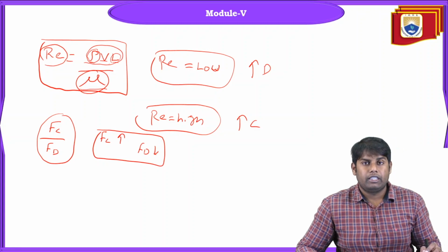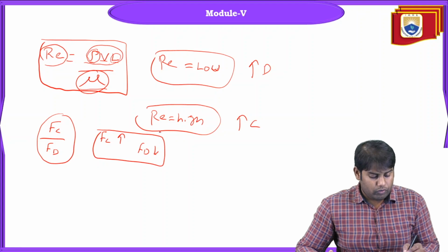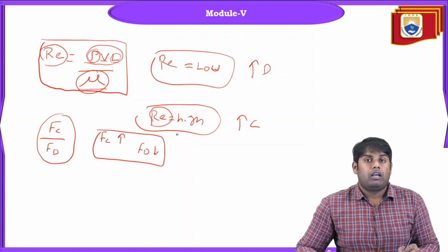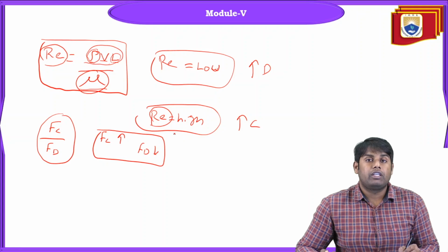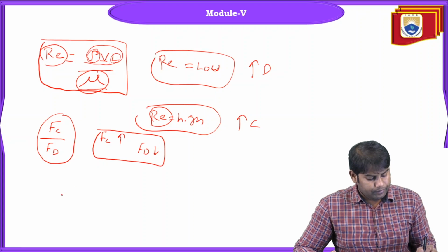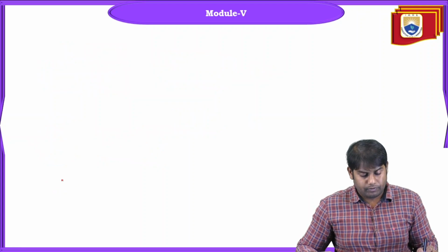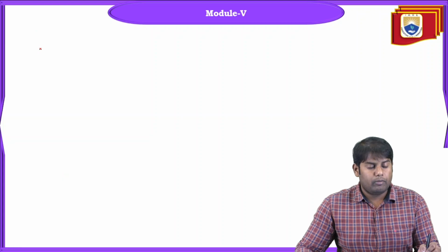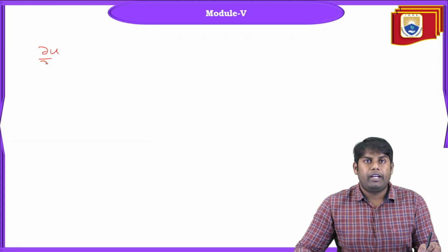Having this knowledge, when you non-dimensionalize it, we have the Reynolds number as a part of the equation in the momentum. So let's say you have the general momentum equation, which is dou u by dou t, where the first term corresponds to the unsteady term, or the local derivative term, plus v dot del u.